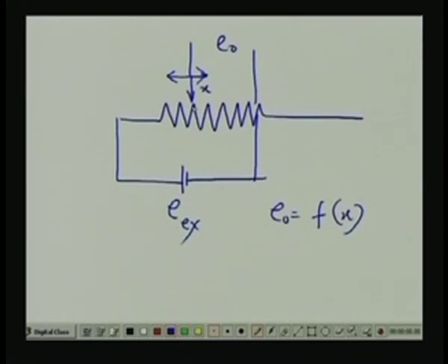Regarding resolution, you see that whenever there is a potentiometer, even though I am showing here that it is getting contact with only one turn, the actual potentiometer looks like this one, is it not? So this wiper will always contact more than one or two windings.